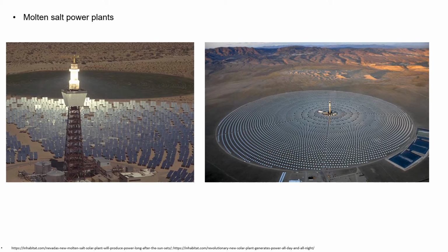In the molten salt solar power plant, molten salt is used as a heat transfer fluid (HTF) and thermal energy storage (TES). The salt used in these systems is a low melting ternary mixture of molten salts with a melting point of 131 degrees Celsius that can be used as both a heat transfer fluid and thermal energy storage of concentrated solar power plants.